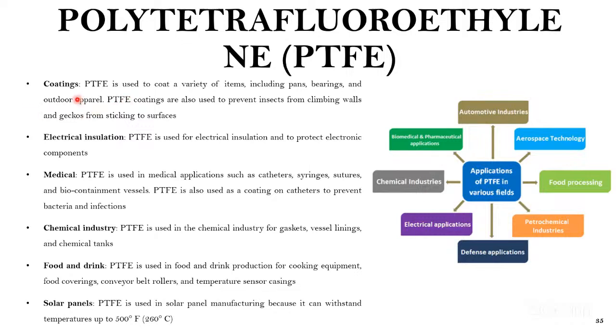And in outdoor apparel, they also do PTFE coating. PTFE coating is also used to prevent insects from climbing the wall and geckos from sticking to the surface. For a few of the walls where hygiene is majorly required, they use this PTFE coating because PTFE is highly hydrophobic in nature, as its cohesive energy is quite high.